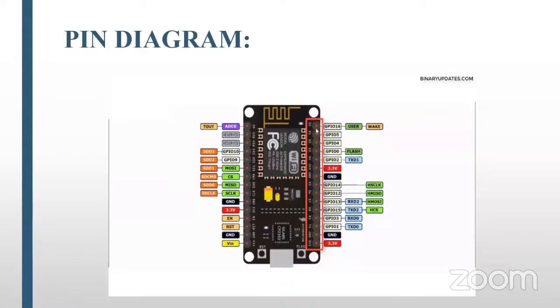If you monitor the room temperature using that pin, the room temperature value will be 20 to 33 degrees Celsius. Via that pin, we can easily monitor the temperature. But via digital pins like GPIO 1 and 3, we cannot monitor analog values. Why? Because those digital pins do not have an ADC. They give the output as 0 and 1 only.